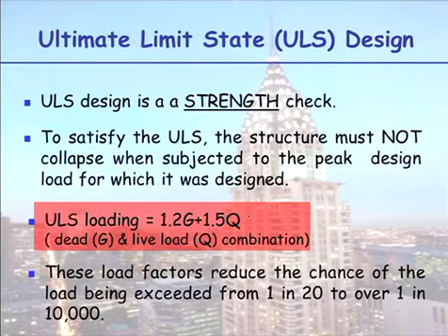Now you may think that's very extreme, but the consequence of something failing is people being hurt, okay, is fatalities. So these load factors reduce the chance of the load being exceeded from 1 in 20 to over 1 in 10,000. So now our odds are a bit better, or a lot better. And that is the way we design in Australia. There used to be something called permissible stress design, but I won't go there. Okay, that's our ultimate limit state design.